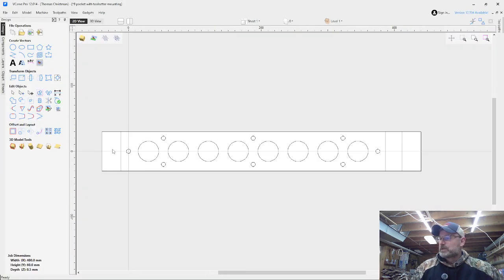I use Vectric, and if I open up my Vectric here, you can see I've brought this up. I have this basic file, and I have the tool length setter, which is right in this position here, so it adds that on there. Then you can use all of these to pocket out your different things. There are two spots: this pocket, this one here, and this circle here are the exact sizes I used to pocket in for these pins.